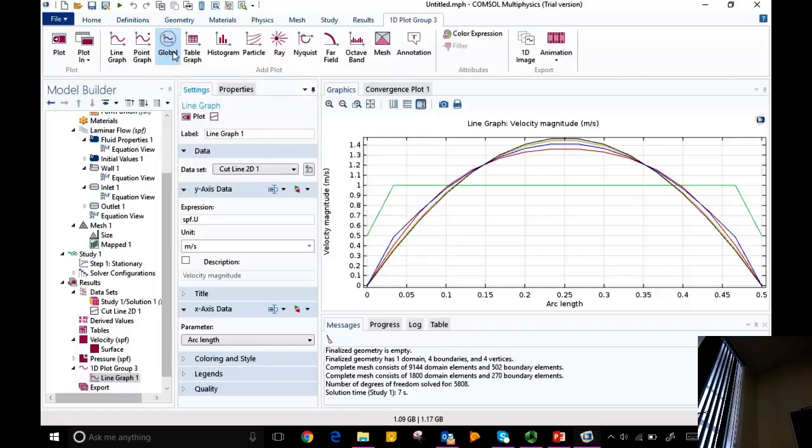So if I approach this point, so I'm plotting the velocity variation on that particular one. If I approach that point from this side, the velocity is 0. If I approach that point from this side, everywhere the velocity is 1 here. So at the corner, is it 0 or 1? And that you call a singularity, right? What it does is take the average, 0.5. So the 0.5 is coming from that fact.